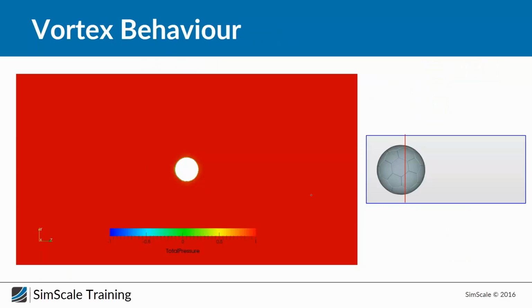Yes, and finally, I would like to take a look with you at this vortex structure. So therefore, we have created a slice which is going through the ball in X direction and visualizing total pressure. So here you can see our actual position. We start just before the separation occurs. And then you can see how the separation bubble is created. And this is very important. This Magnus effect will change the whole overall structure of the ball and of the wake of the ball. And here you can really see what is basically happening. We have this unsymmetrical wake.